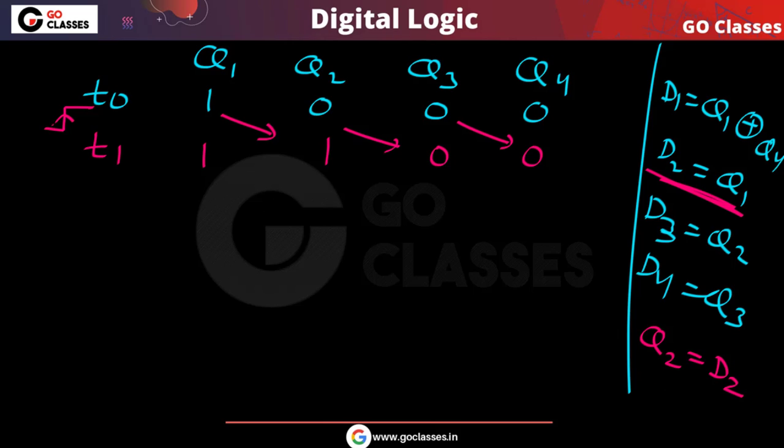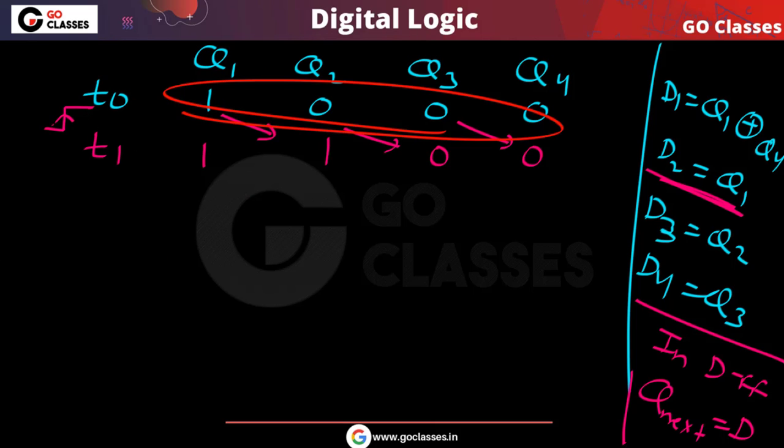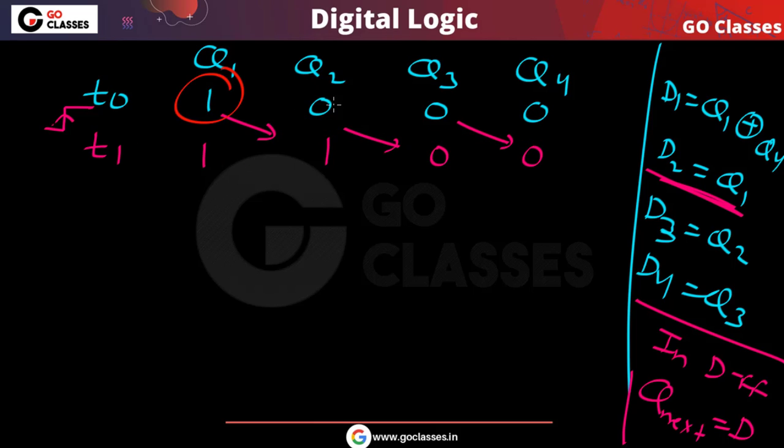In any D flip flop, you already know that Q next is equal to D. So at time t equal to 0 this is the initialization, and after one clock pulse, 1 exclusive or 0 is 1. So this will be 1, and this one will be shifted here, and so on. After the next clock pulse, after one more positive edge, what will happen?